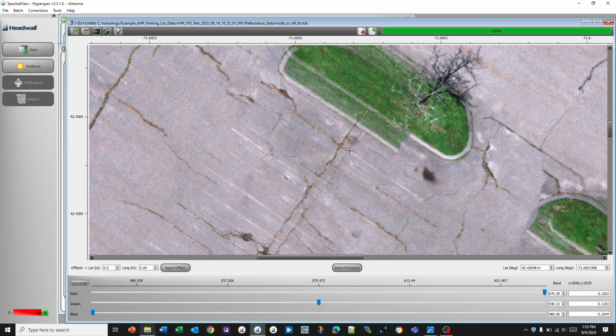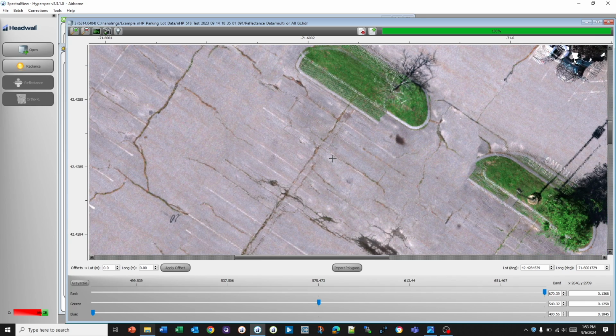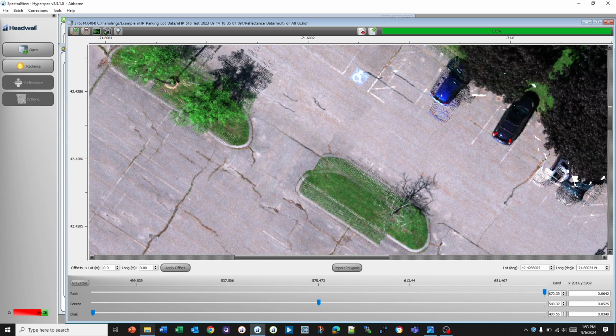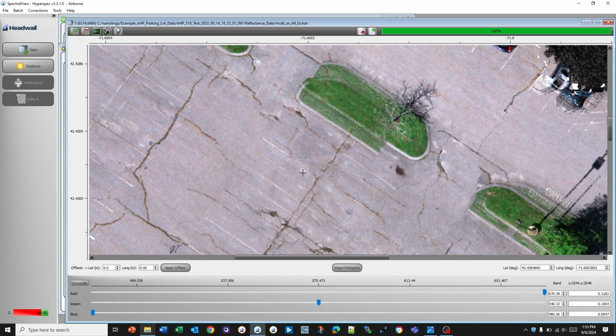And so the correct way to go about processing this is to adjust for pitch and then look at one of the overlap regions. So we would adjust for here and then look at over here. If we can get this area to line up, but this area does not, then that means we have a yaw correction needed. Similarly with roll, if we can get this to line up, but this to not line up, then we have a magnification error.